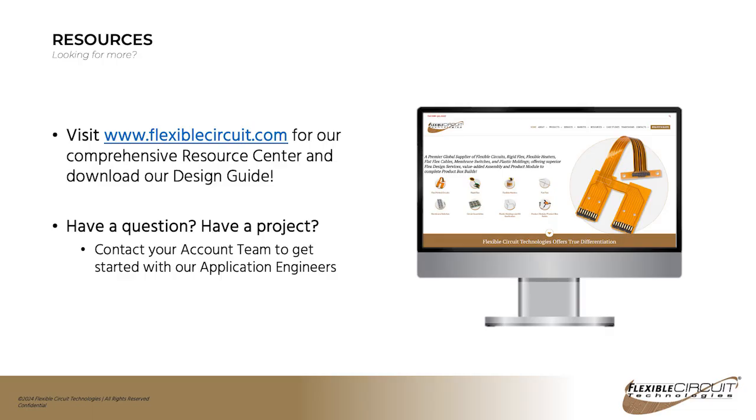How do I terminate a flexible circuit? There's a number of different ways. Again, pretty much any connector that you can put onto a rigid PCB, you can also put onto a flex. Again, you're going to want to make sure that you have mechanical support for those connectors, because those can be high strain areas, and you want to make sure that you don't damage your circuit when it's moved around.